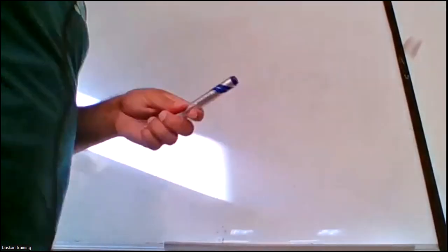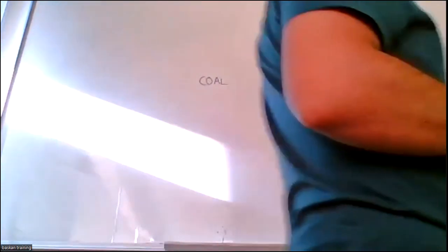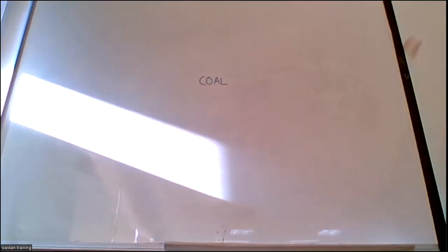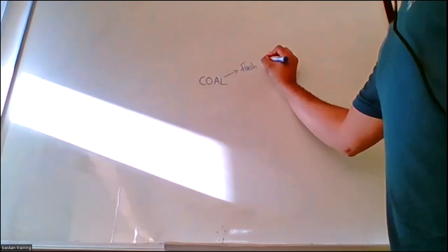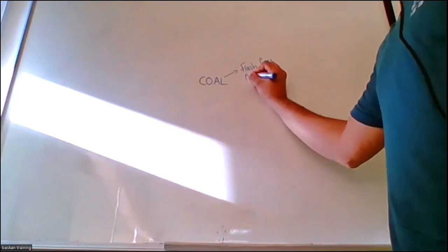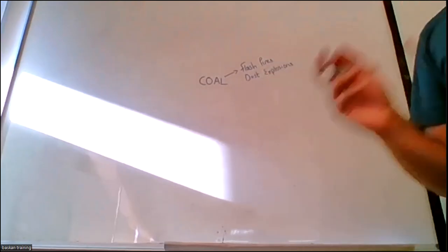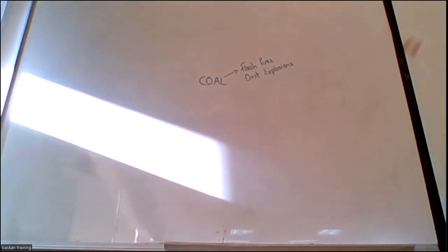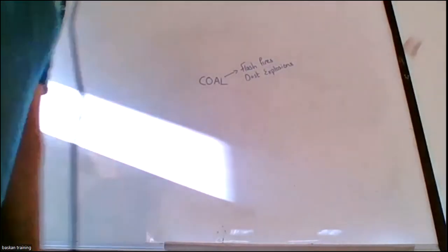And then we'll discuss wood. Okay, so coal itself. Different types of hazards are associated with coal. Okay, that can lead towards flash fires and dust explosions. Why? Because coal, whenever it's stored, tends to give off dust into the atmosphere. So that area needs to be ventilated. The second important parameter about coal is that it tends to give off carbon monoxide into the atmosphere. And carbon monoxide, we have already discussed, tends to displace oxygen very effectively, right?